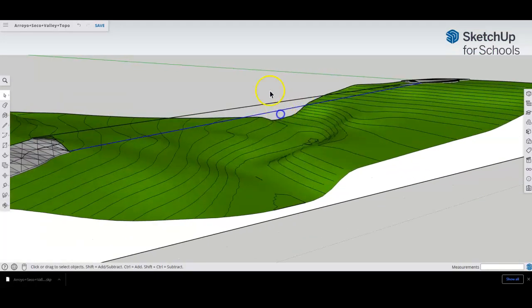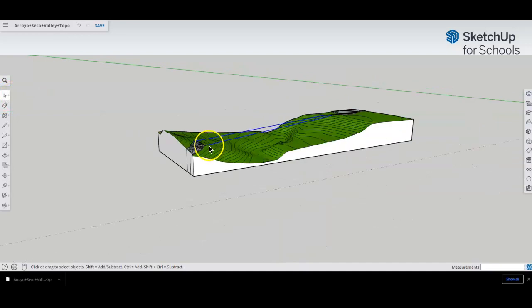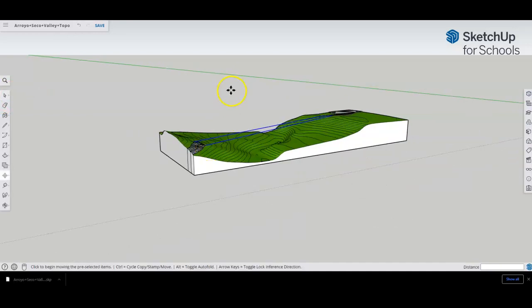And I'm going to go ahead and make a copy of this. So I'm going to hit the space bar for the select command, and I'm going to grab these. So move, the letter M for move. I'm going to hit control. You see that plus sign right there, right next to my cursor. So I'm just going to left click, drag, and I'm going to drag right here on the grain.